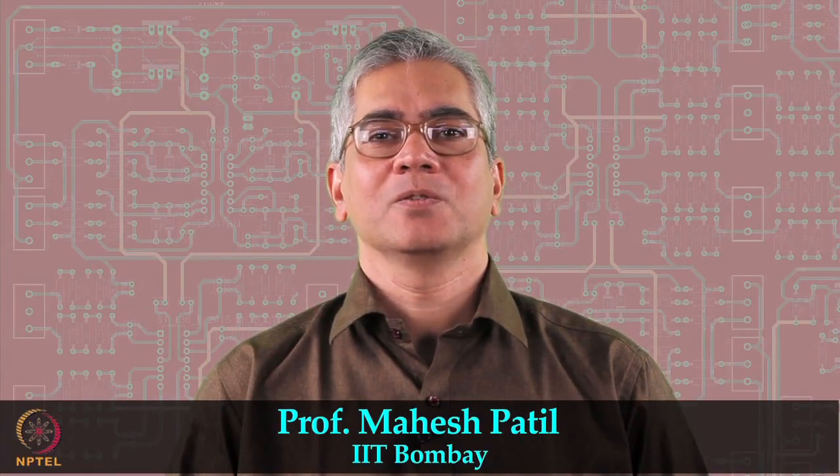To summarize, we have found expressions for Rin, the input resistance, and Ro, the output resistance of the non-inverting amplifier. We found that Rin is very large and Ro is very small, and that makes this circuit very useful in certain applications. We also looked at the op amp buffer, which is a special case of the non-inverting amplifier. In the next class, we will look at how a buffer can be used to avoid loading effects. Until then, goodbye.